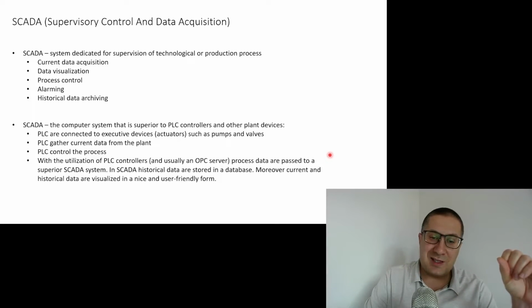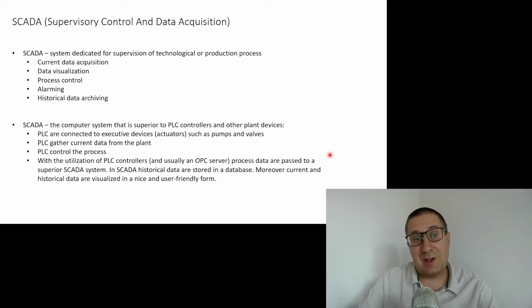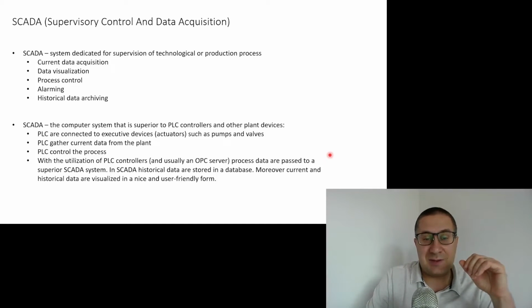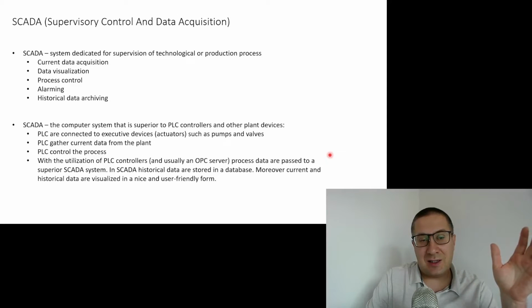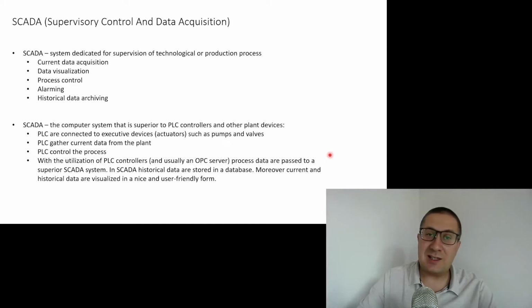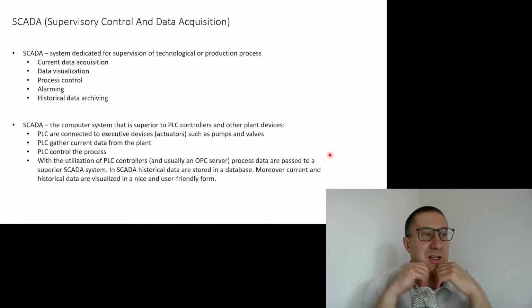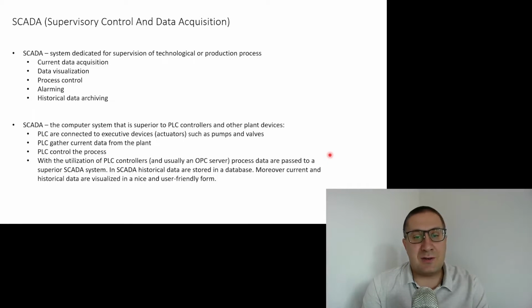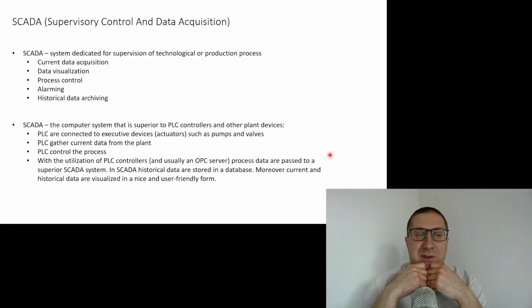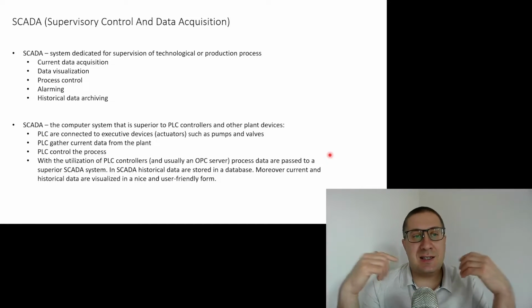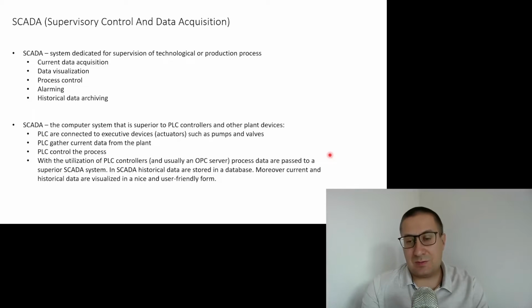We can use, for instance, the OPC server to connect the SCADA system with the PLCs, or use some industrial protocols that are usually handled by PLC controllers and the SCADA systems. If everything is provided by one vendor, usually there are dedicated drivers, so the connection is easier. If we want to connect to the SCADA system because we would like to read the data and send our decisions to the control system, we can also use, for instance, the OPC server or a dedicated driver.